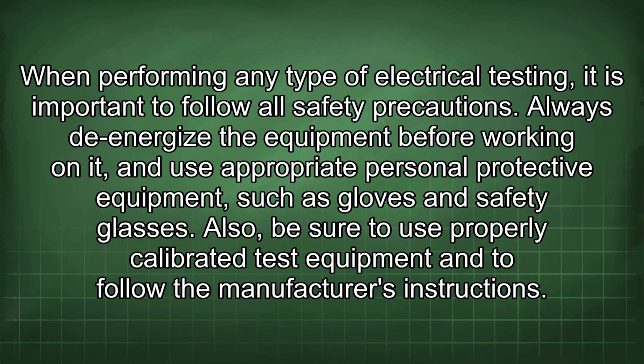When performing any type of electrical testing, it is important to follow all safety precautions. Always de-energize the equipment before working on it, and use appropriate personal protective equipment such as gloves and safety glasses. Also, be sure to use properly calibrated test equipment and to follow the manufacturer's instructions.